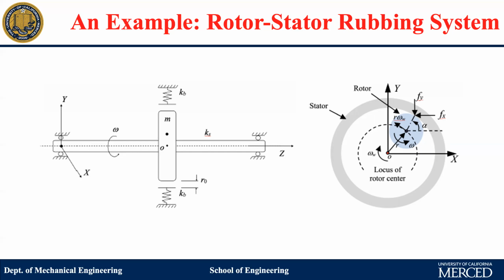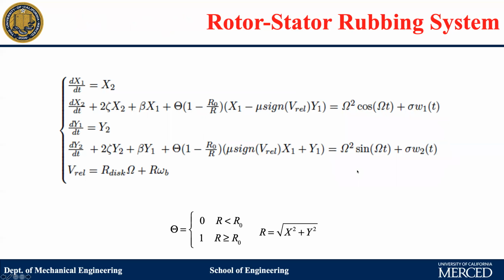At some point, the rotor will touch the supporting boundary, and then the equation of motion, with probably a first-mode approximation of the shaft, is a fourth-order, or four-dimensional, state space nonlinear differential equation. So these are the equations.